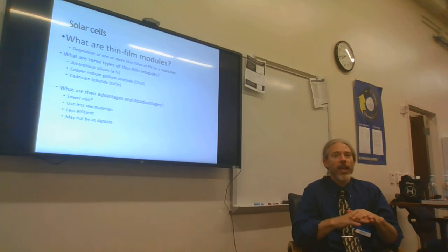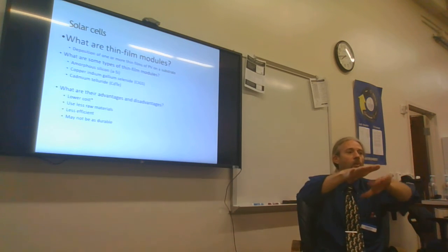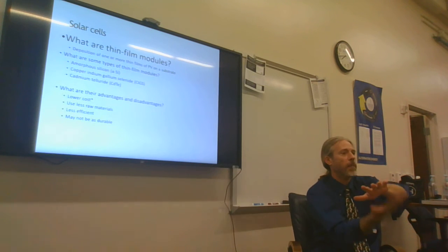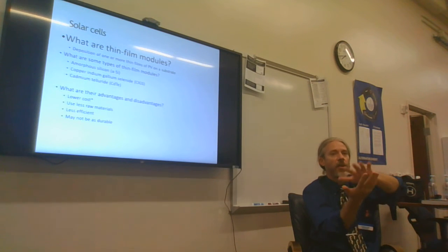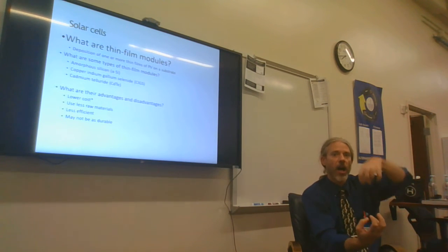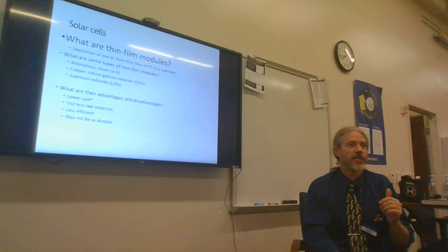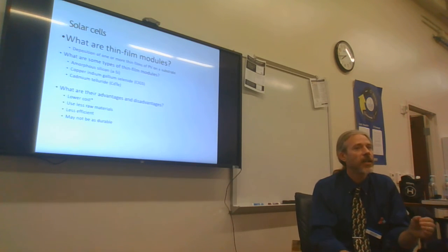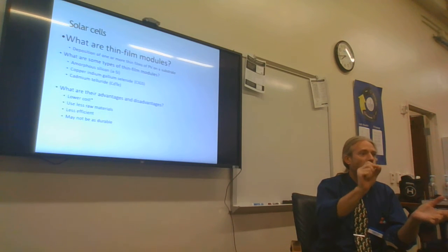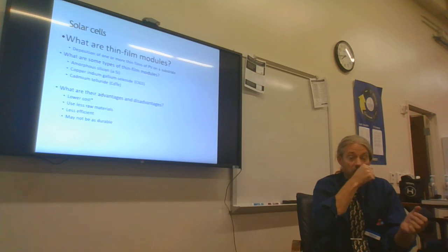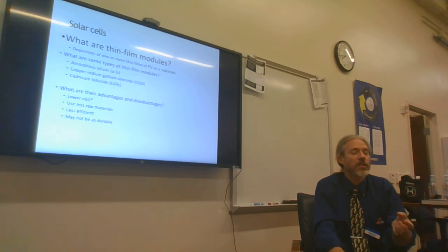I can even add to that. Remember how I talked about we have an N type and then we have a P type? Well, what would happen if I would put another N type on the bottom of that P type? Now I could actually produce power whether the radiation hit the bottom or the top of the cell. Now we have a bifacial panel. That is exactly right. All we've done to the whole cost of manufacturing is add one more tiny layer to one component. So the cost of manufacturing a bifacial solar panel is pennies more than the cost of manufacturing a standard monocrystalline solar panel.